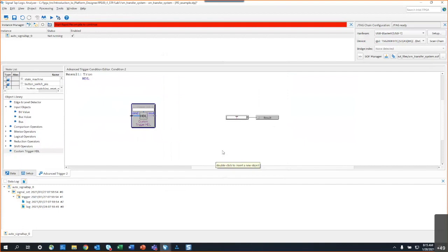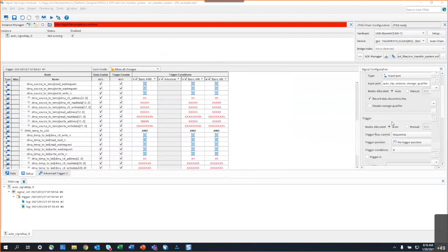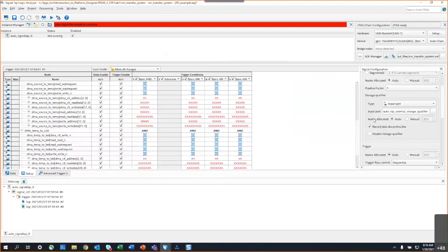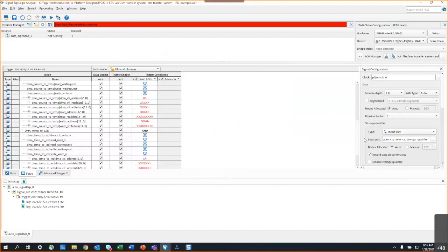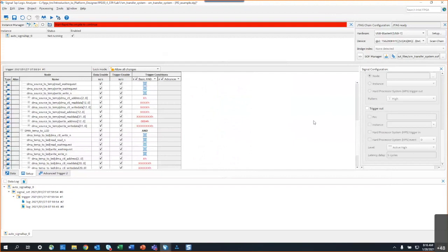Okay. Next. So the next question is they're using SignalTap on a Stratix 10 SX dev kit with Linux running. So Linux configures the FPGA in the second stage bootloader and the kernel boot up. So the FPGA gets configured while the HPS is booting up. Afterwards, when I set up the JTAG connection, 24 megahertz does not work, and the error says the FPGA is not configured. However, when I switch the JTAG connection to 6 megahertz, it works. And why is that?